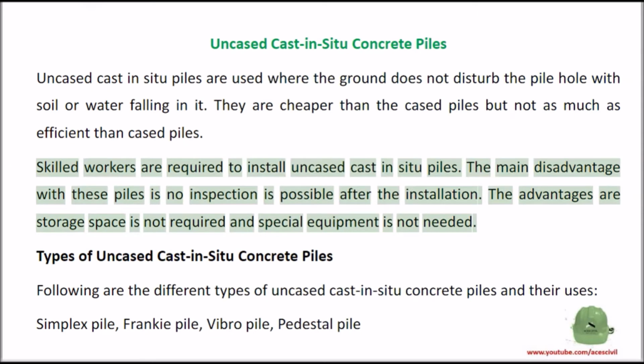Skilled workers are required to install uncased cast in situ piles. The main disadvantage with these piles is that no inspection is possible after the installation. The advantages are that storage space is not required and special equipment is not needed.